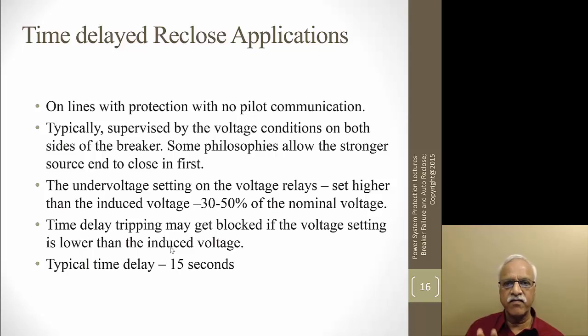You have to wait for 15 seconds for the springs to charge, and that is how this has been historically set. It can be set lower, to 5 seconds. Yes, you can do that if it is only one shot. If you have multiple-shot reclosing, then you have to have an interval of at least 15 seconds to allow the charging mechanism to restore the spring charging during reclosing.